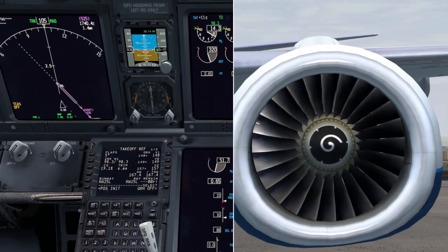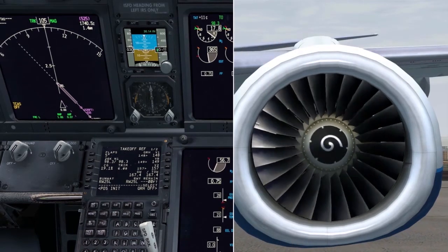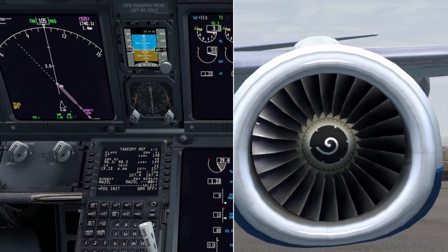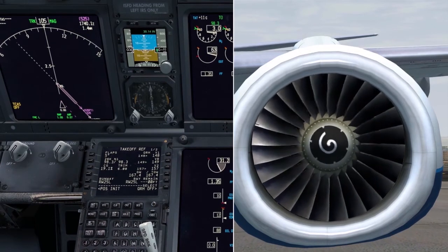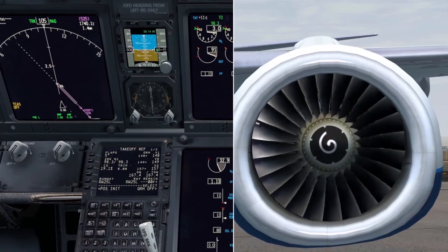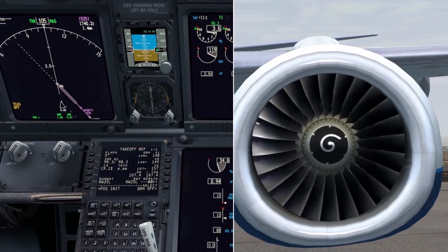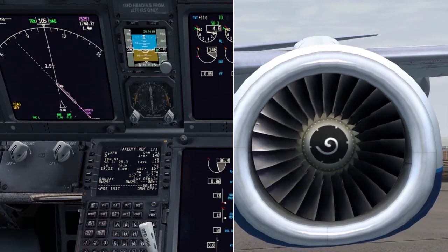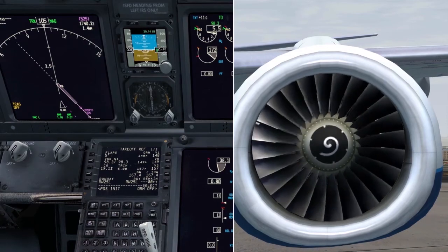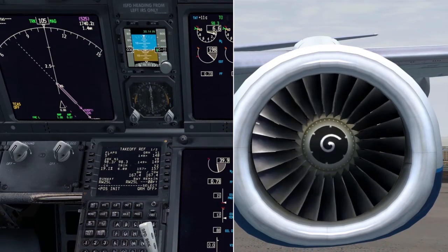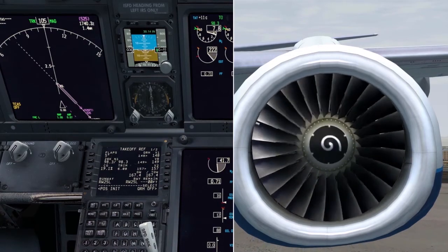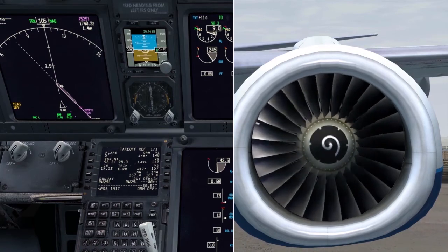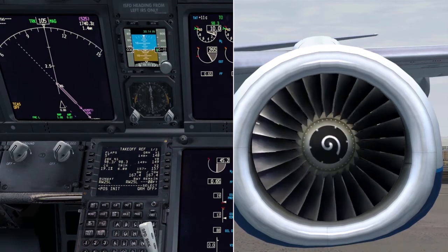The engine starter turns the engine N2 high-pressure shaft through the accessory gearbox we mentioned earlier. The engine starter manages to turn the N2 shaft by converting highly pressurized air into mechanical energy. This high-pressure compressed air is pneumatic power that is usable when the start valve opens.